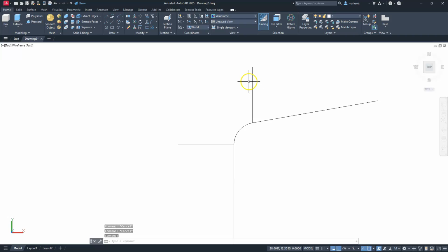Well, we need this one to actually rotate going backwards 10 degrees. So if I'm able to select it here, and then I can select this blue axis, I'll go ahead and turn my ortho off. And now I can kind of see which direction I need to spin this. So I need to have it going back this direction. Once it's going that direction, I'm just going to type in 10, and it should rotate it back 10 degrees.